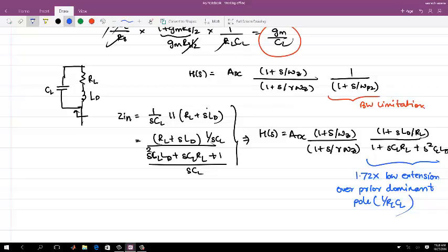This is what you can prove. And the important parameter is, using this inductor, you can always get more peaking. But more peaking is not good, because if you are causing more phase distortion in the channel, in the equalizer response, that is going to hurt.